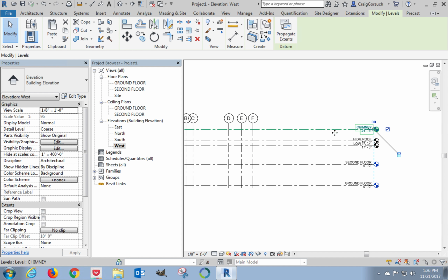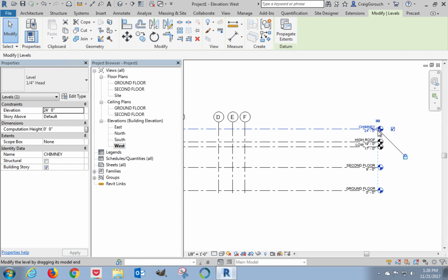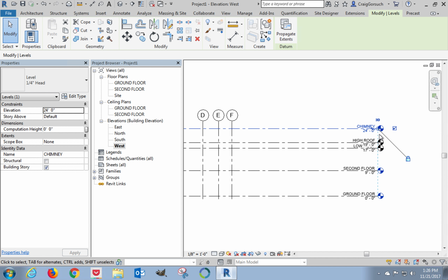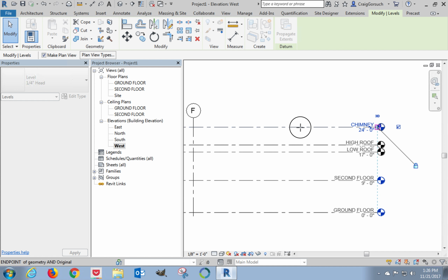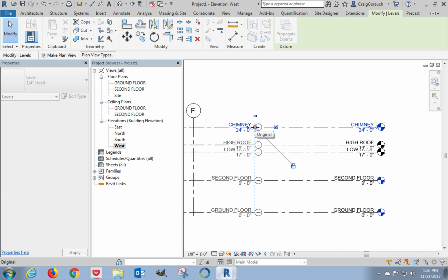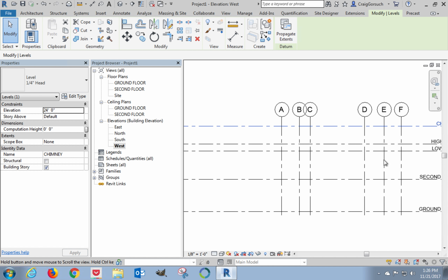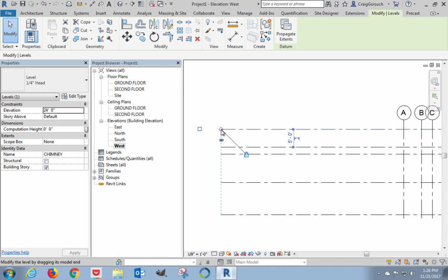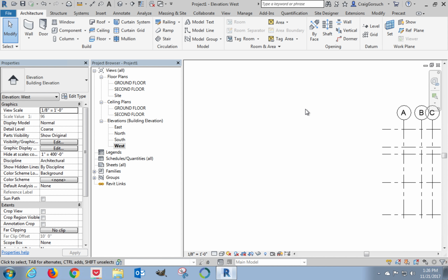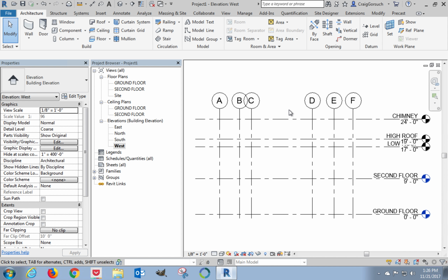And I'm going to select a level. Now again, I'm zooming in so that I can get that little open circle. That's what I'm aiming for when I do this. So I'm going to click that little open circle, and I'm going to pull this in this way. Come back over here. There we go. There's the other end. Left click, drag him over. There we go. Double click my scroll wheel, and that's my zoom extents.